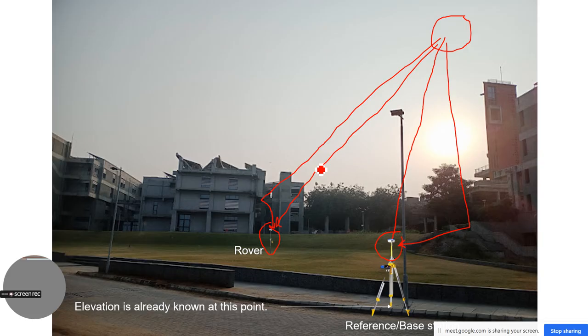Anyway, the main principle of DGPS is that you have one particular point whose location is known to you. If in your area it is not known, first you get the data of that station. So when you are doing a survey where points are not available, it is relative to the one point which you are fixing. In that case also it will remove the satellite error and atmospheric error, but it is with reference to the base station.